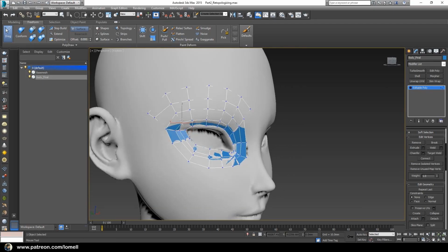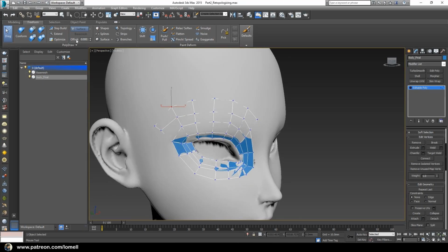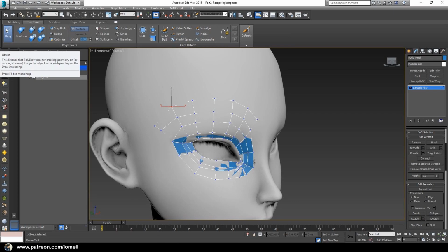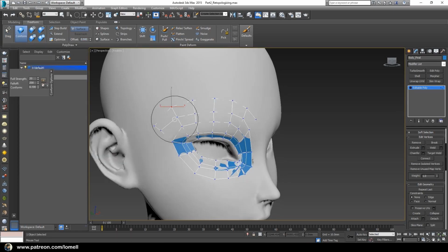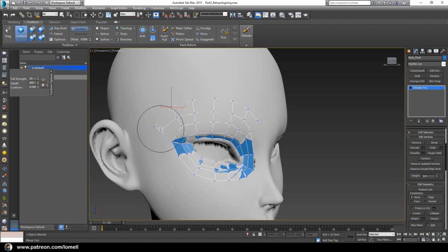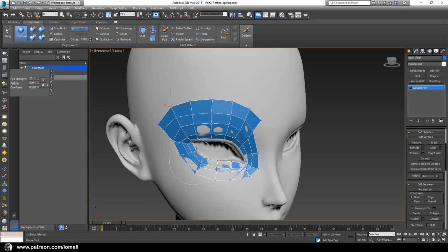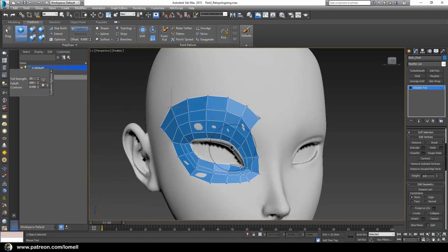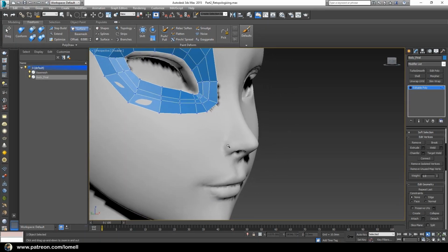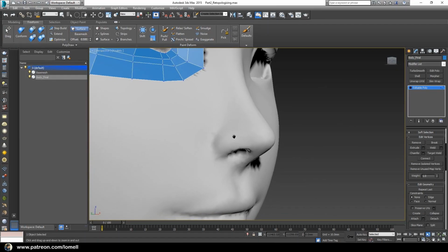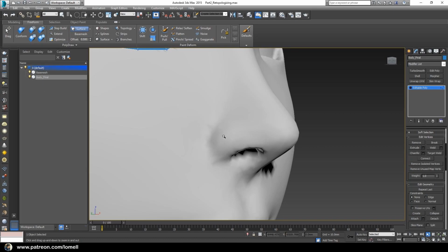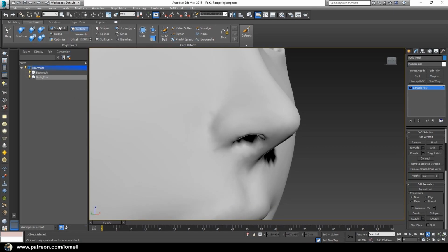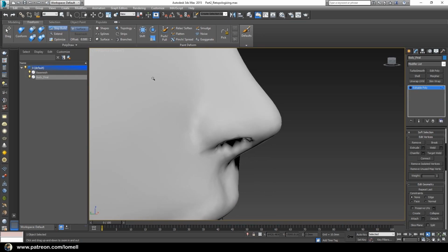And if you can barely see the surface, we can just confirm this and offset the surface to 0.5. I think that's enough, so let's confirm the surface at 0.5 and click and drag. All right, and now I'm ready to start over on some other areas of the surface, so maybe here at the nose. I'm going to use step build again.